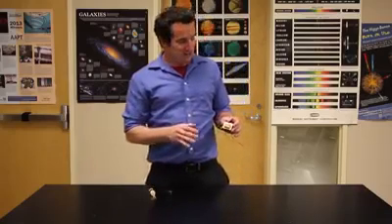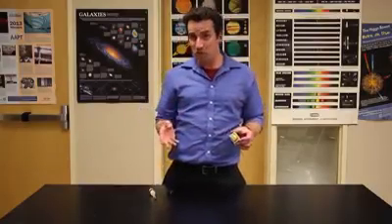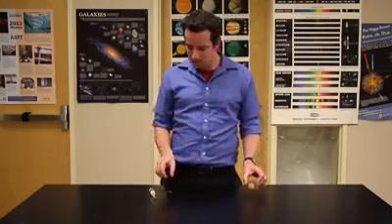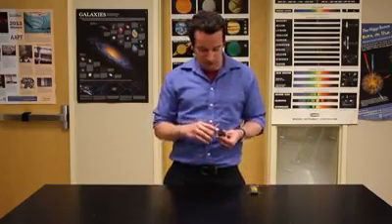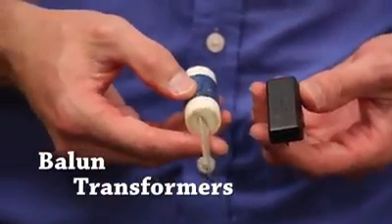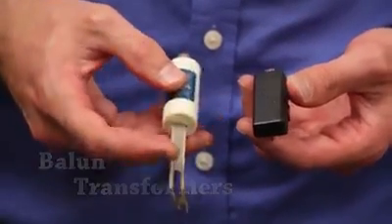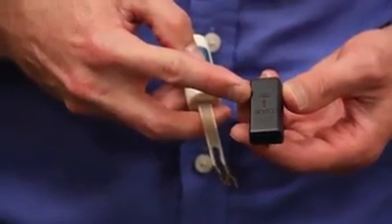One more thing. Since transformers have to match impedances in order to work, it would make sense that you would have different transformer constructions for different frequencies. These are high-frequency transformers for television application. These are Balun transformers that are used to match the impedance of the 300 ohm flat TV lead to the 75 ohm impedance of the coaxial cable lead.